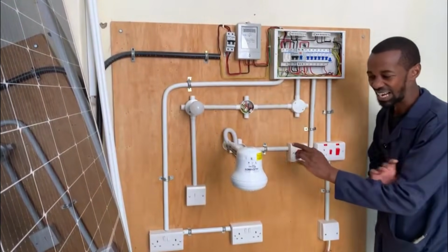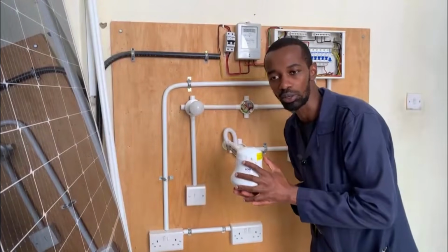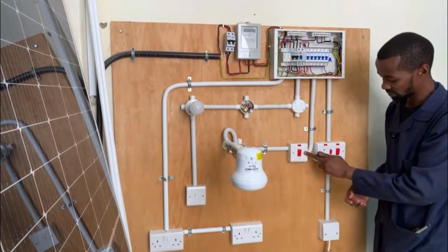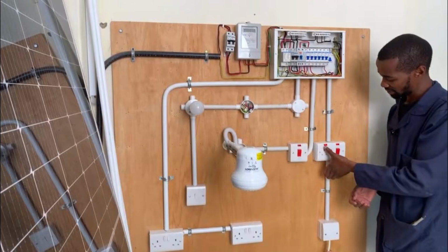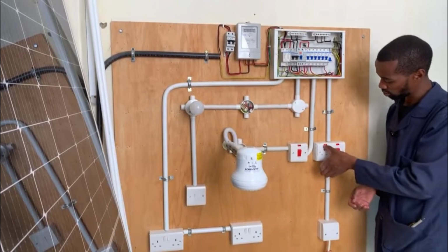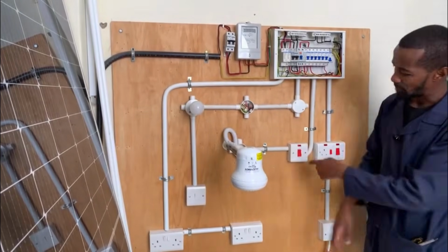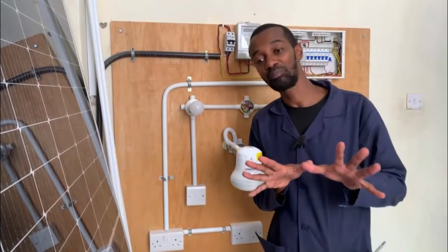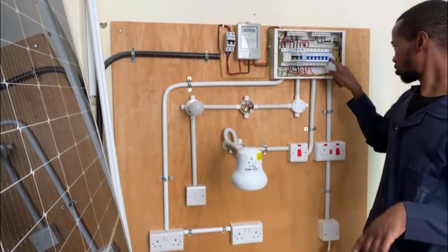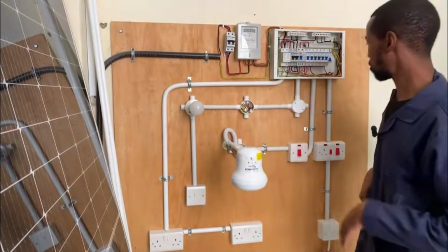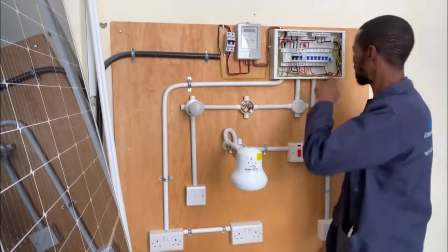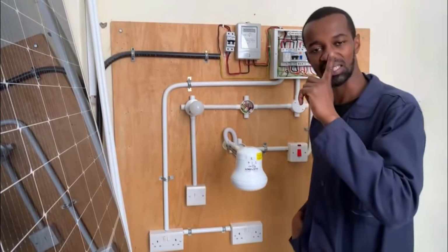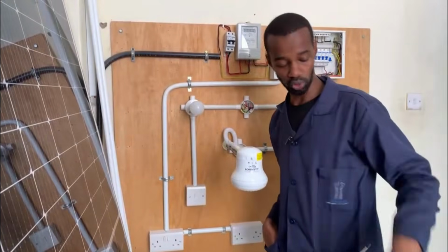This heater here is powered on. You can see that light. I don't know whether you can see it. It is on. This cooker unit is on, but the light here is not turning on. Those are some of the very important questions that you ask your customer. So the MCB is down. Now, once you visit the customer, you have seen that the MCB has tripped. You start troubleshooting.